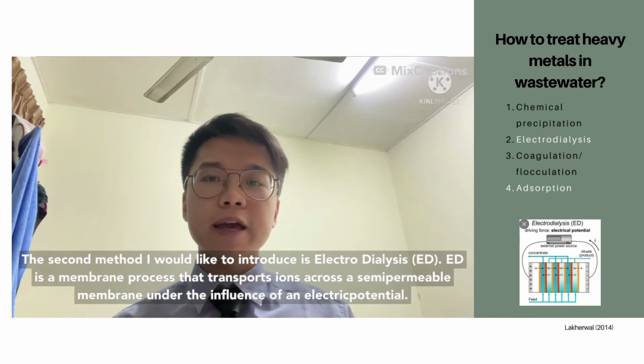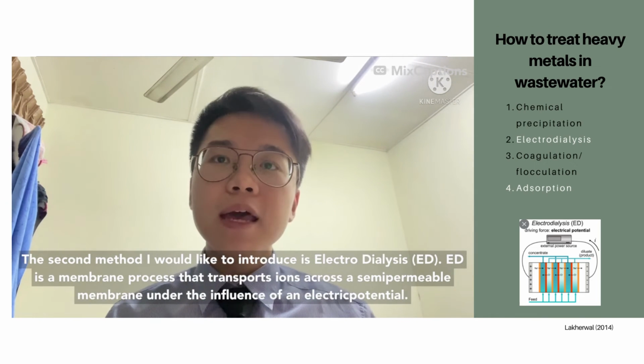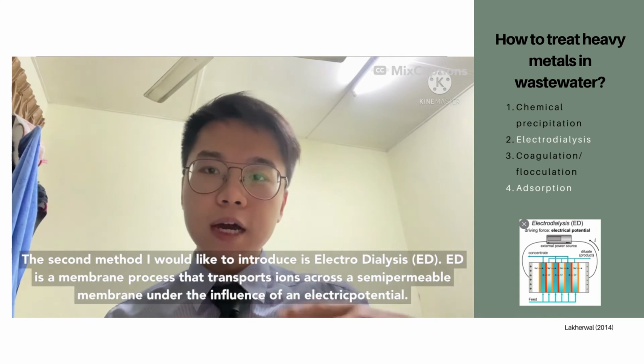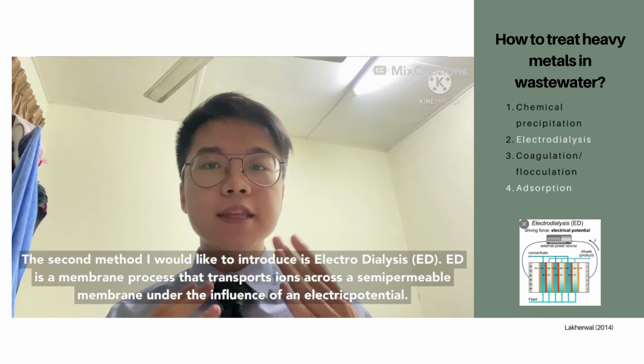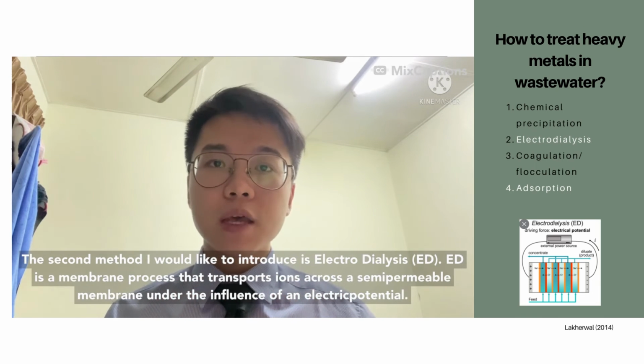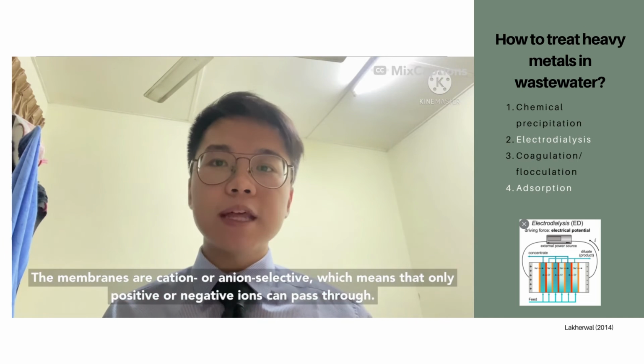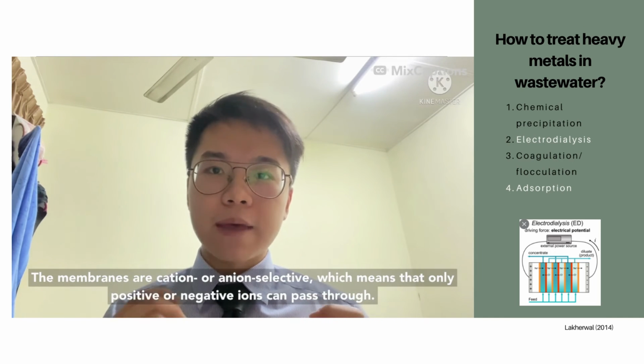The second method I would like to introduce is electrodialysis. Electrodialysis is a membrane process that transports ions across a semi-permeable membrane under the influence of an electric potential. The membranes are either cation or anion selective, which means that only positive or negative ions can pass through.